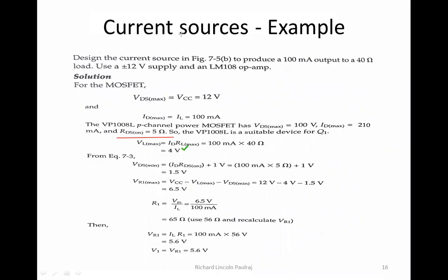Please check and tell me if we're getting about 1.5 for VDS minimum. Again, what is VDS? The voltage between drain and source. Correct. Drain and source.